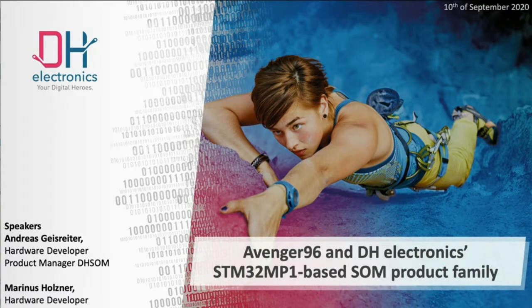I take the question again. It's me, Marinus, and for the DHCOM module, the pluggable system, we have the family design. So yes, when it comes to the pluggable systems, you can of course upgrade your baseboard or your complete product by simply changing the SOM, because all of our future SOMs in the DHCOM form factor will be compatible with this form factor. But like mentioned, with a family design, you sometimes have to make a compromise when it comes to all the features which are available by the SoC.